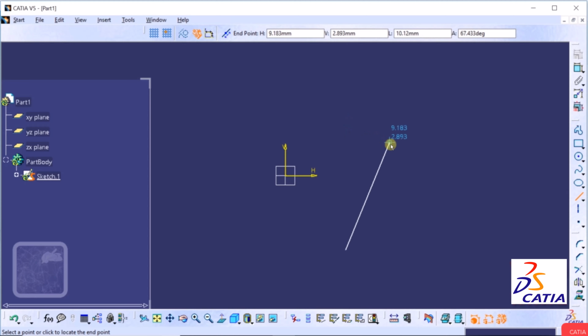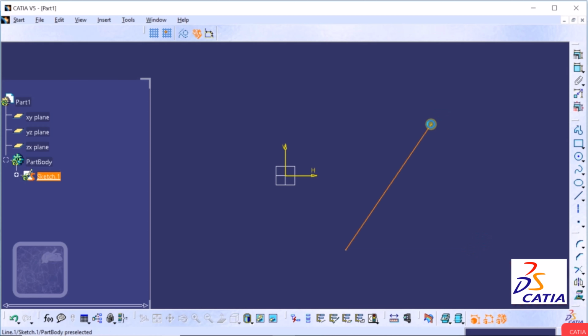Similarly, when I take it to the horizontal direction, we can again see the symbol of blue. It means the software is trying to apply constraint into this. So we are going to cover this automatic constraint later after this manual constraint. So let's say I select this point and click here. And then I want to make this line horizontal or vertical. So how can we make this?